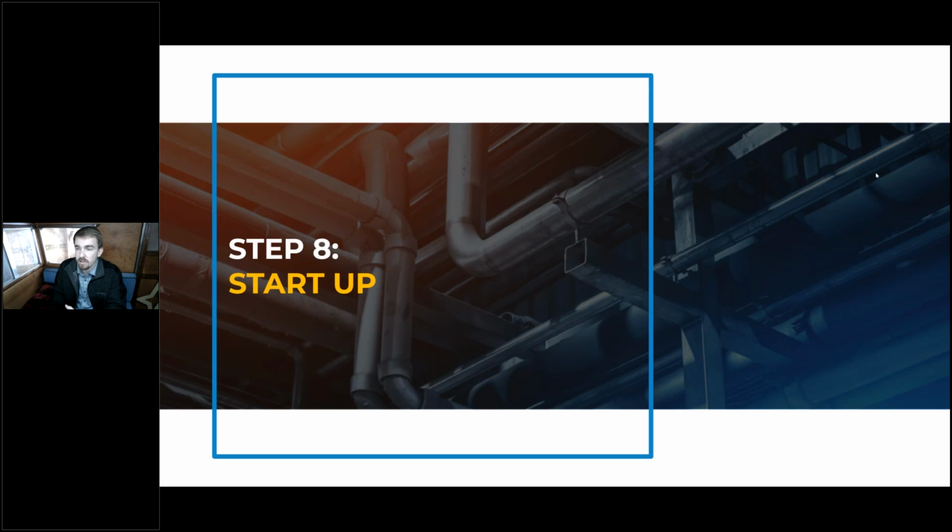So the gas water heater can just be paired with that swing tank, or you can use an existing gas water heating system to serve as that swing tank. That would provide the swing tank heating when the primary storage isn't sufficiently charging that tank, and it would provide redundant backup in case the heat pumps go down for any reason. So that's where I've seen boilers work there.